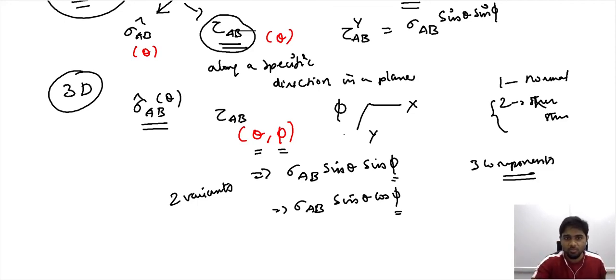So with this, we will wind this lecture up. What essentially we have seen is the components of stresses and how they vary with the system that we consider. In the pseudo three-dimensional case, it's just two components. In actual three dimensions, the stress for an inclined plane can be distinguished into three components, one normal component and two shear components. Goodbye.